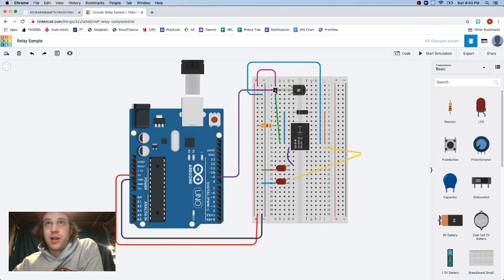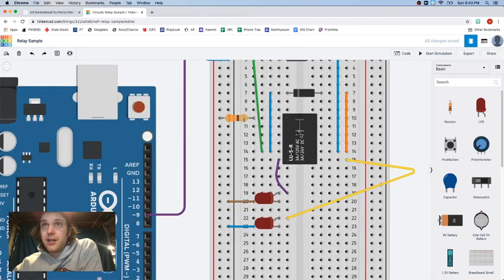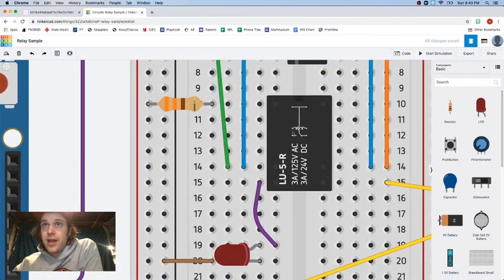So when we turn port 9 on to high, now electricity is flowing through the emitter, down this wire all the way into this channel, and it's going to come through here. We have a parallel circuit bouncing off to go to this flyback diode, okay? But don't worry about that now. It's going to come through, and if we look at our circuit, there's our coil. There we have an inductor.